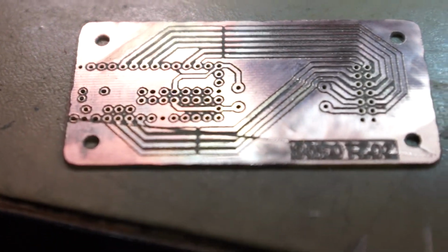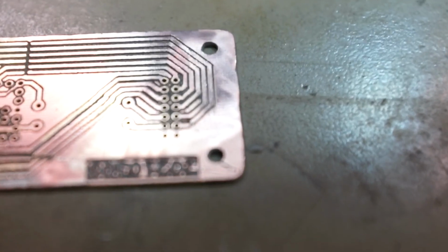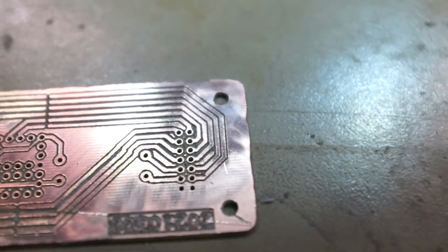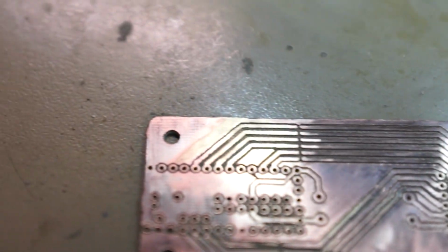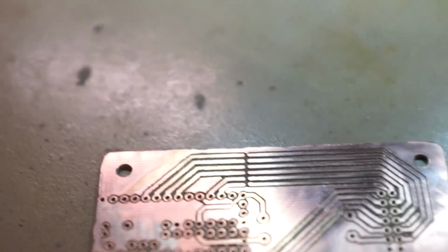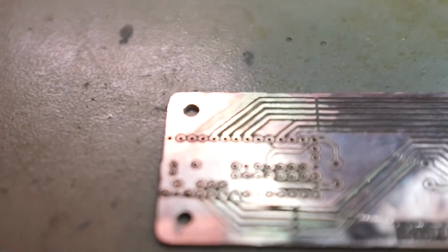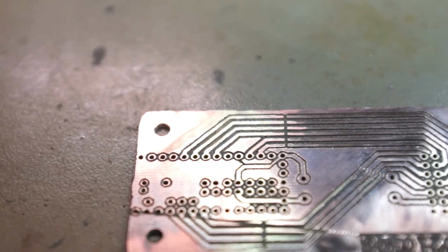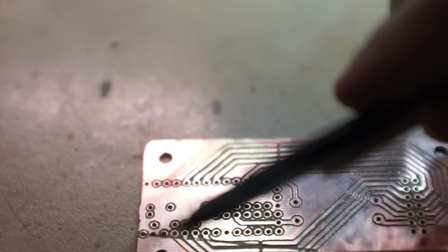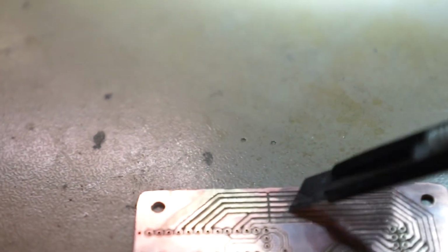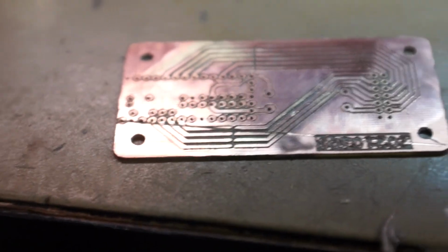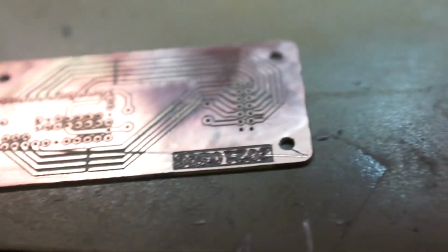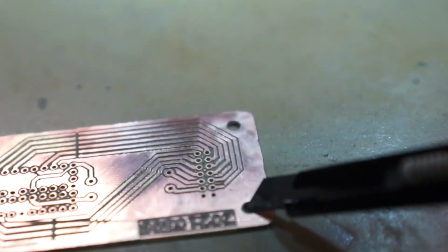So here we have the board after some polishing and some rework. Clearly the quality is gonna get better in the future, but some of the things I had to do is scratch away a little bit of leftover copper there. The problem is when you mill away stuff and you leave a tiny trace, that tiny trace ends up wiggling back and forth, so it was touching this trace sometime and then the other and then the other, effectively short-circuiting the 2 traces.